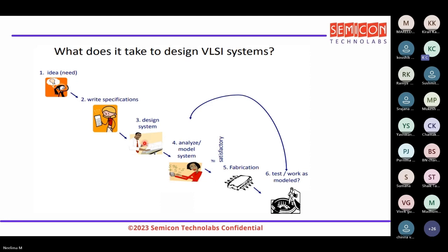We go again a little deeper from the third step, to see where we can further optimize our implementation. And from here, if it is satisfactory, we start our design process. Once the design is completed, of course, physical design is also part of this fourth step. Once everything is completed, including physical design, it goes to fabrication, where we saw one of the foundry people taking the IC out of the wafer, 1.5 centimeter by 1.5 centimeter. So that's how the IC comes.